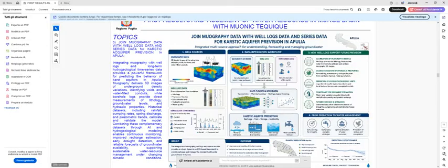So we are probably also planning to install a meteo station to evaluate the evapotranspiration, as a next step. How do well logs support this future vision of muography? For the calibration of muography models, well logs provide real lithology, fracture, and water level data to calibrate and validate muography 3D images. Characterization of hydraulic properties, permeability, transmissivity, and specific yield from well tests improves model parameters.